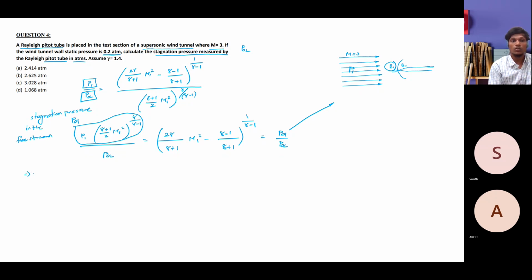It's an application of the theory that you learned in previous chapters that you have to apply here, whether it is an experiment on supersonic or subsonic fluid flow. If you apply the same thing, then you first need to find P01, because we need to finally get the value of P02, that is the stagnation pressure behind the normal shock wave. Though we can simply solve it, we just try to rephrase things so the picture is clear about what is involved in this entire equation.